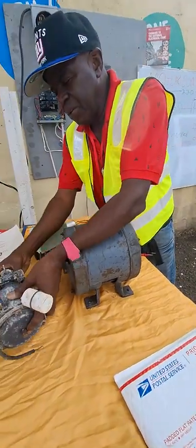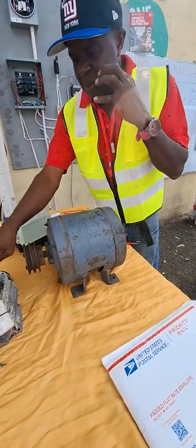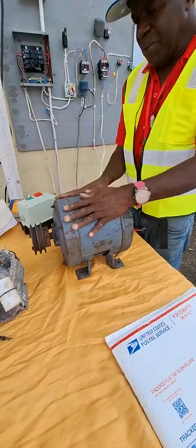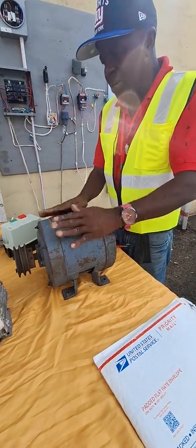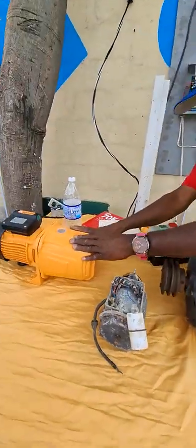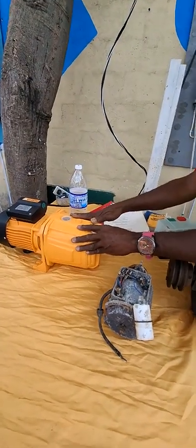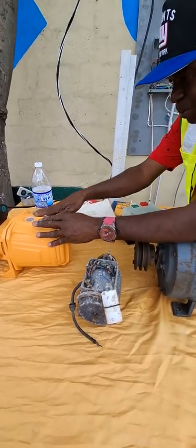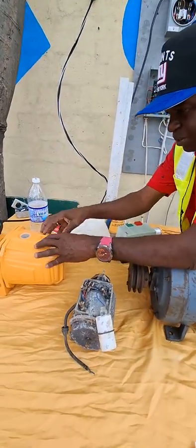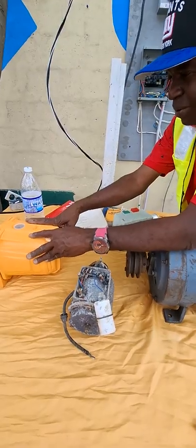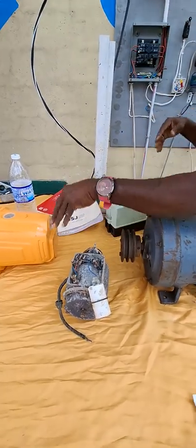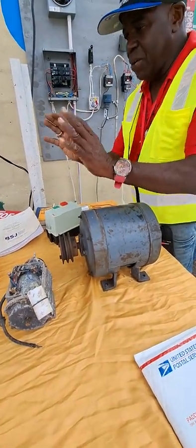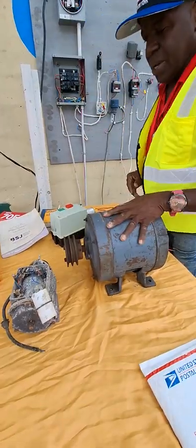The motor is normally supposed to provide torque to cause things to work. So, a simple motor: the 3-phase induction motor is a self-starting motor with 3 windings, whether connected in star or delta. And the simple single-phase motor normally has a starting winding and a running winding. It also has a centrifugal switch. When the starting winding kicks the motor into starting, the centrifugal switch takes out the starting winding and allows the running winding to continue to run.